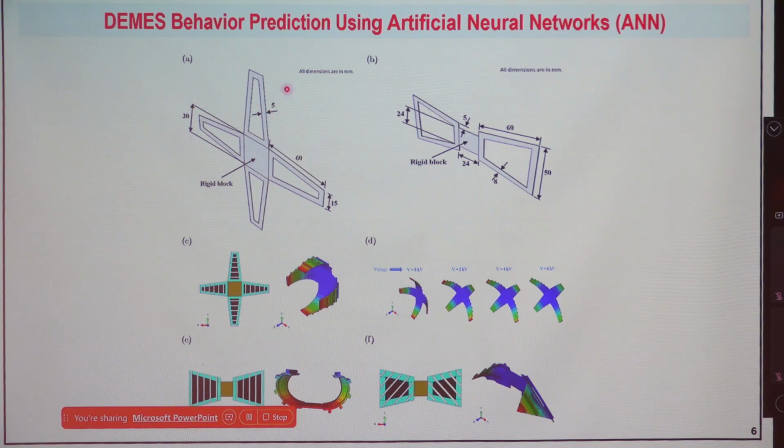If you see here, in finite element simulation, I have told you it is a very rigorous and tedious process. One simulation takes 6 to 7 hours for getting one initial equilibrium angle. And for one experiment, since this acrylic elastomer VHB has strong viscoelastic behavior, after pre-stretching we have to keep it for 24 hours for stress relaxation.